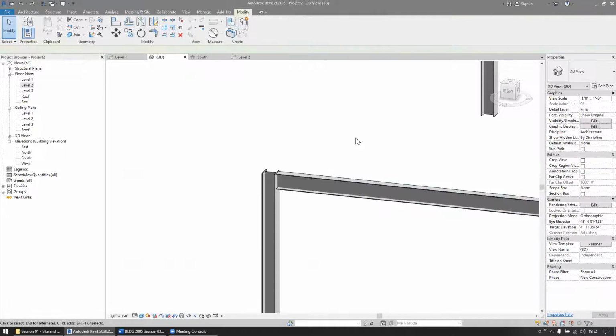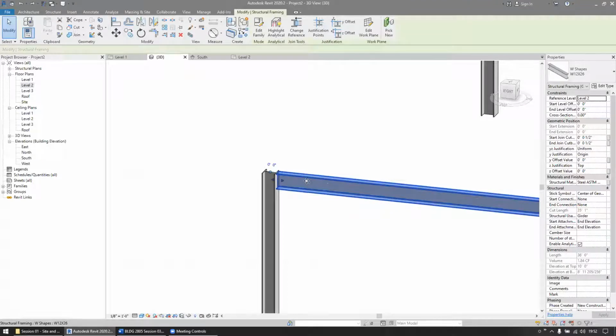So what is the difference? Okay, so the circular dot is, as far as Revit's concerned, the actual end of the beam, the structural end of the beam. So what's happening with this beam? This beam is carrying loads over to this column. And basically Revit says, yeah, the loads from the beam are being transferred to the centroid of our structural column and then down to the ground.